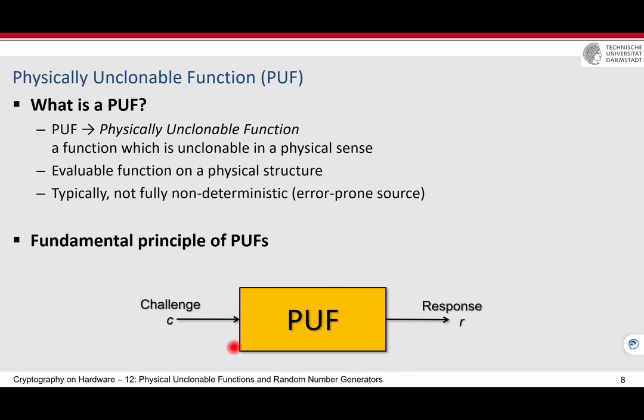And if you fabricate a chip with completely the same structure, produced 100 times with exactly the same design, then for each of them, if you send a challenge, which is, for example, n bits, like 64 bits, the response is not necessarily the same for every device. This is a unique response for every device. And it's also not clonable. Even if you fabricate many of those chips, finding two devices whose response is the same for every challenge that you send to them should be impossible.